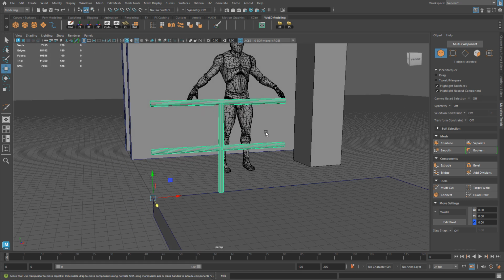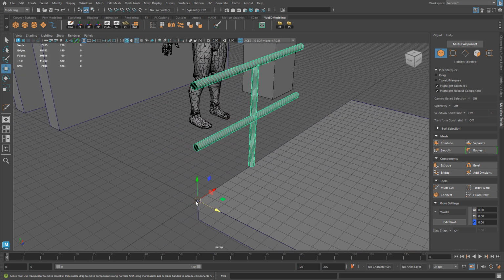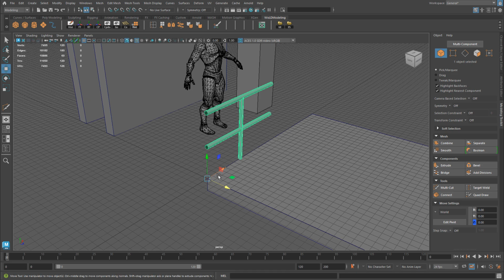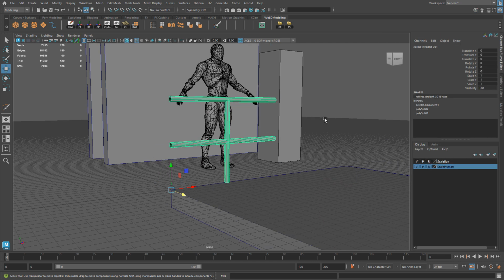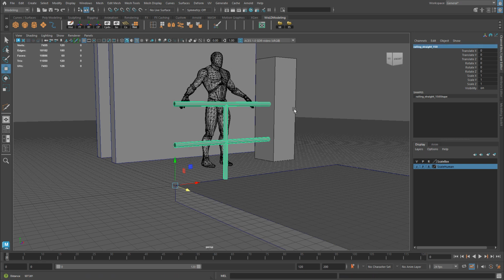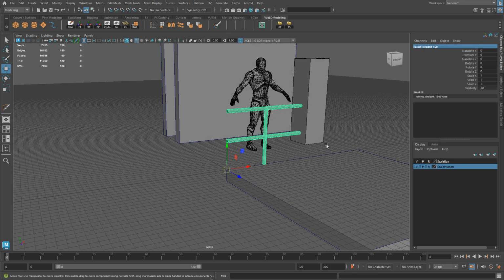Once you have one modular railing created and you have your cylindrical width, depth and height and everything already positioned how you want it, creating additional pieces from an existing base piece is going to be a lot faster. And that's what we did here. The pivot point for this is going to remain in the exact same spot as it is for the 300 piece. And the last thing we need to do is rename it. Let's delete history first and then name it railing straight, and this is going to be 150. And we have our second modular railing, the half piece.